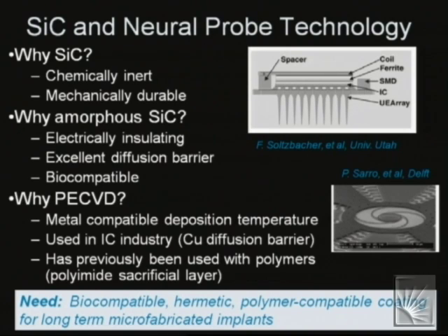So those attributes are what's driving us. Why PECVD? Well, we actually have looked at both PECVD and PVD, but most of our effort up to this point has been with PECVD because the deposition temperatures are within the range or close to the range that's determined by the polymers in which we want to integrate the material.